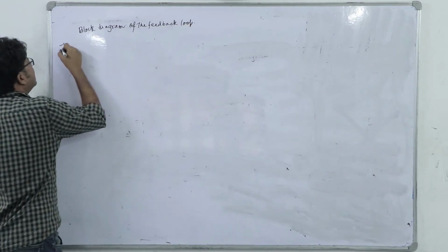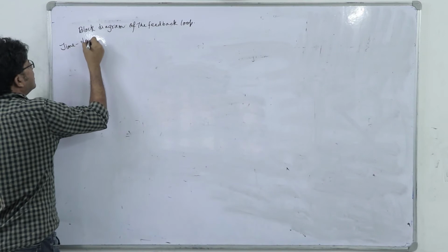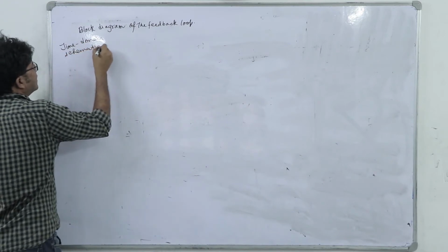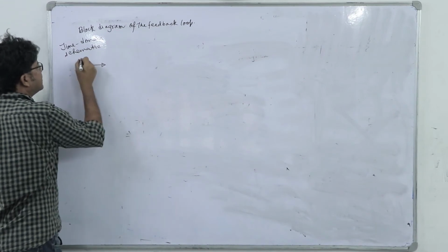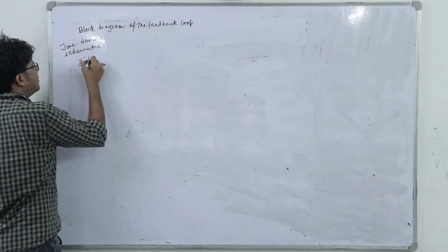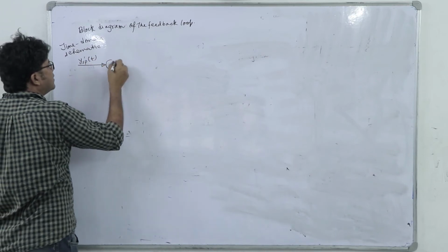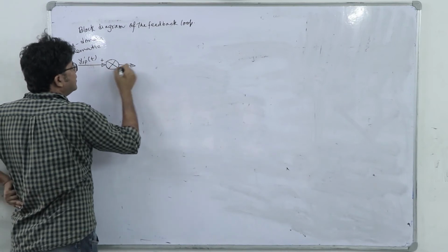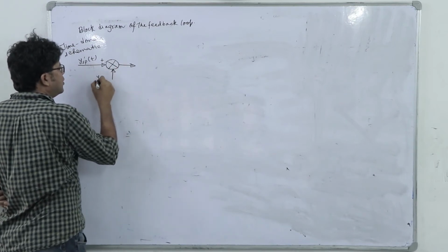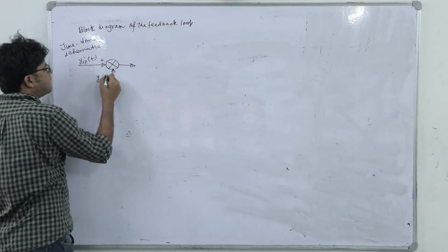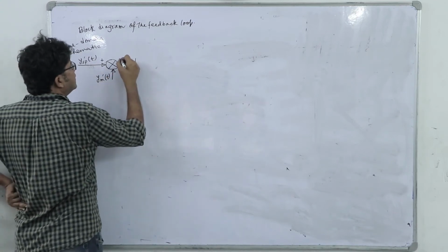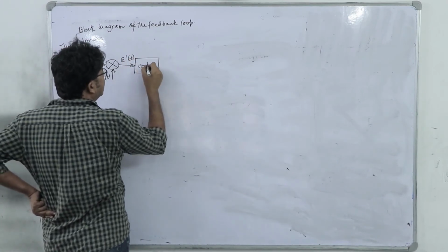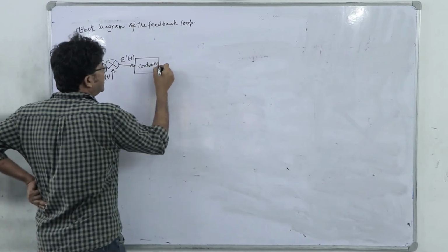So, in time domain schematic of the same feedback loop, here we have the set point Ysp prime t, right, going to the comparator, this is plus, here we have this Ym prime t, right, this is error, it goes to the controller. This is not the block diagram, it is a time domain schematic.